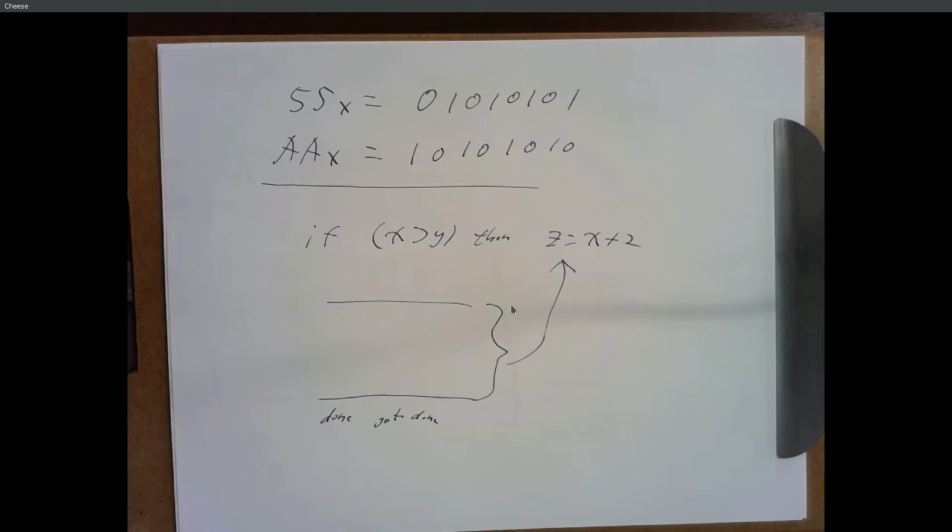If you're using a prescaler of 2-to-1, then every other instruction tick is going to increment your counter. So you'd only have to wait for 4,000 increments. And so you could start at 65,536 minus 4,000. If you make your prescaler big enough, you may only need to wait for 50 increments, in which case you could use an 8-bit timer, initialized to 206, and then after 50 increments it overflows, and so on. So all those details, right? So you'll have some questions related to that.